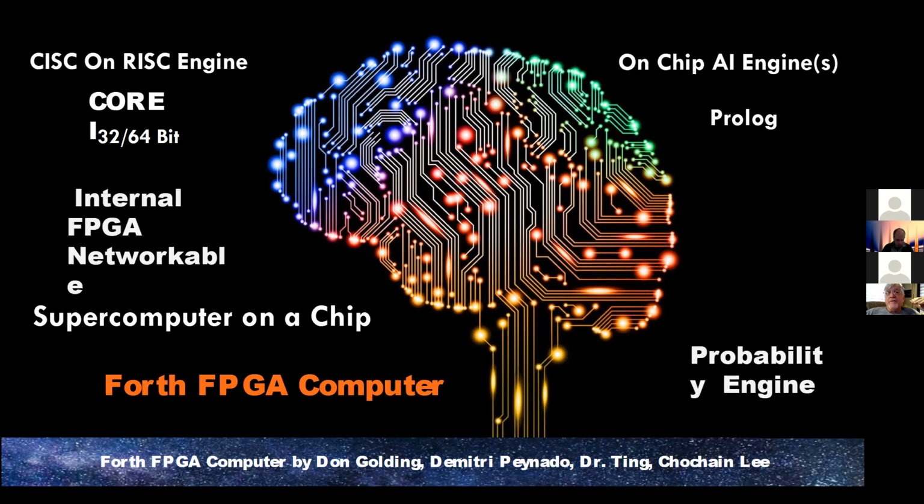It's almost like programming in assembler. SystemVerilog behavioral looks very much like C. It supports typedef, it supports enum, it supports very high-level code, and you don't have a lot of modules that you have to hook together. One of the problems with RTL is you create a module for the arithmetic unit, and then you have to define its IO, and then your main processor executor needs to map to that.